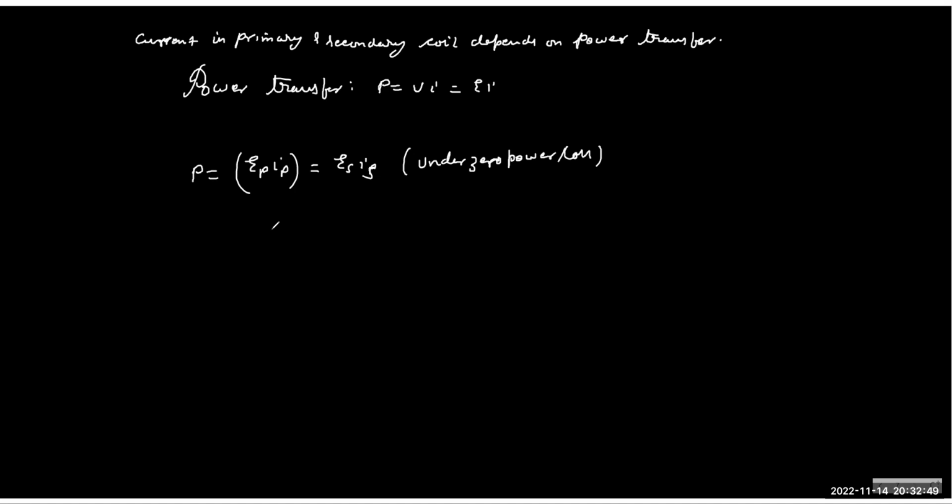then of course, the energy loss could be due to the copper loss or eddy current loss. So energy loss can be due to various other reasons. That's why it is possible even in a practical scenario that there is no flux loss, but there is still some power loss. Okay. And this leads to the relation that the secondary current upon primary current is